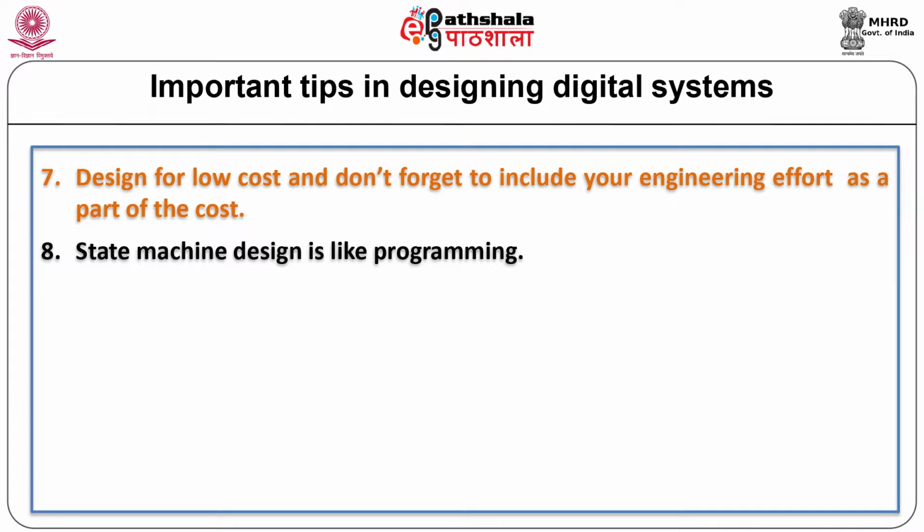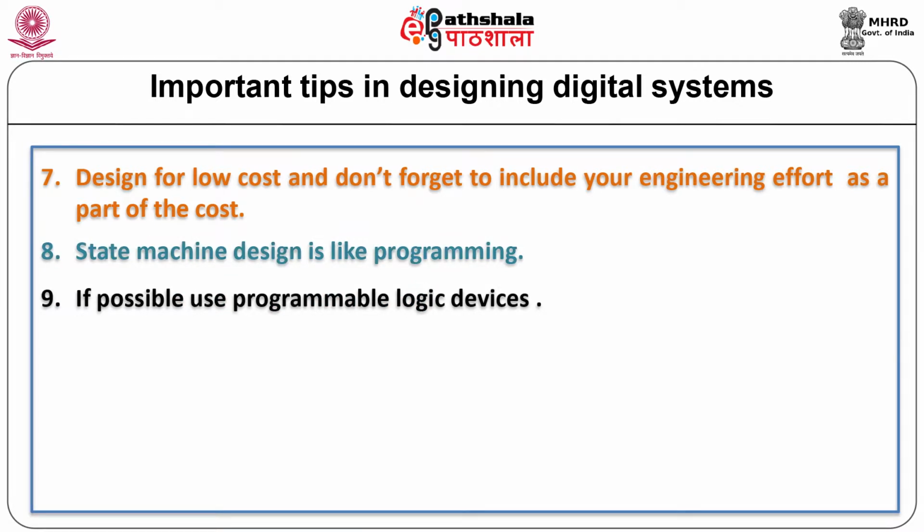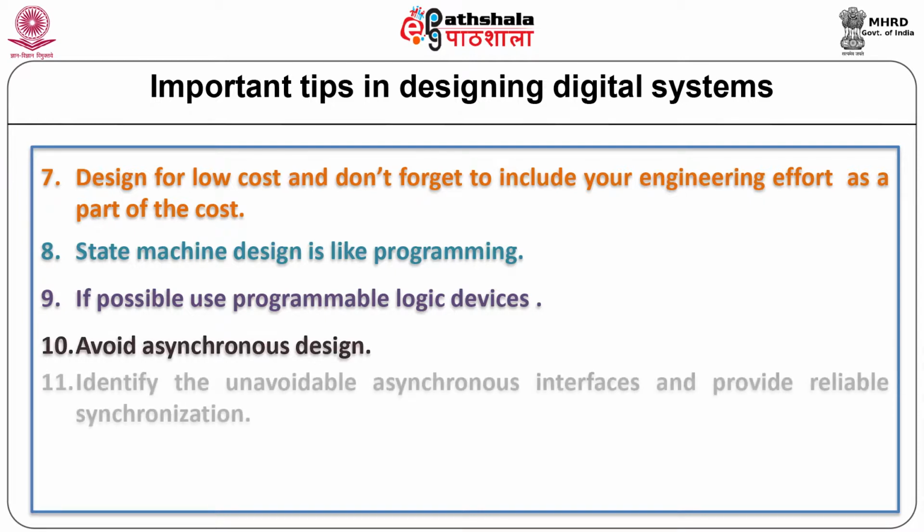State machine design is like programming. Approach it that way. Use programmable logic to simplify designs, reduce cost and accommodate last minute modifications. Avoid asynchronous design. Practice synchronous design until a better methodology comes along.